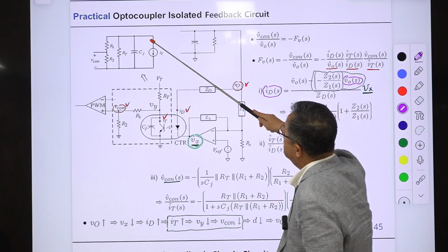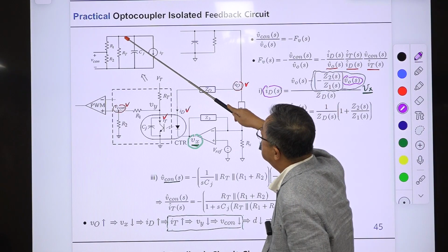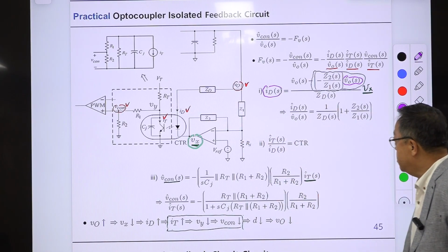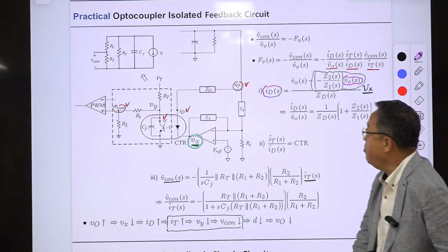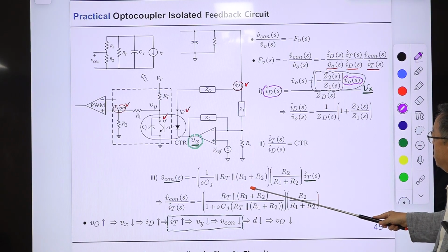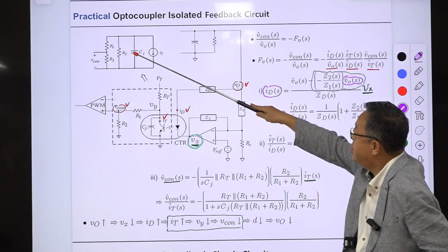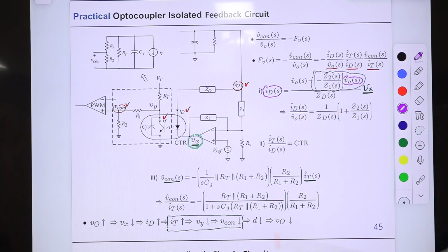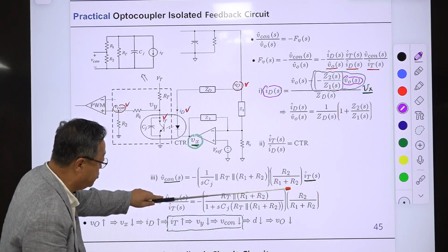Then IT is coming down. Then you evaluate the voltage of this, and that voltage will be divided by this R1 and R2. Okay. So this is the impedance, the parallel combination of 3 branches times IT. IT is the voltage across this, and finally this is just a simple voltage division. Okay. So this is nothing. Okay. Then this is simplified to this.